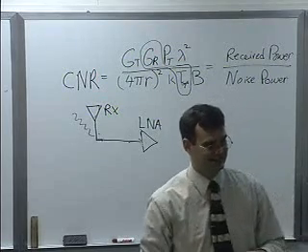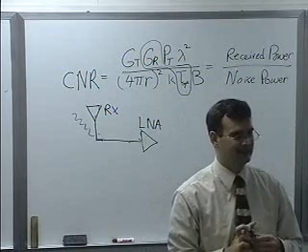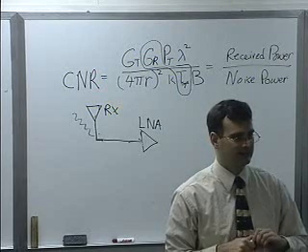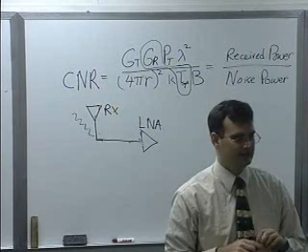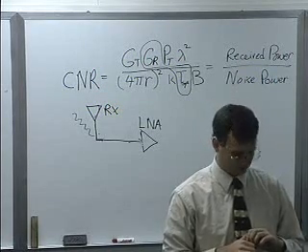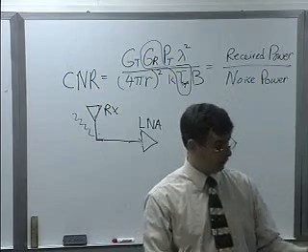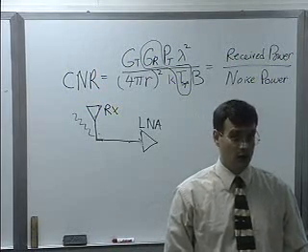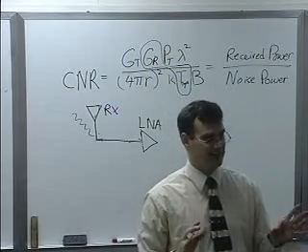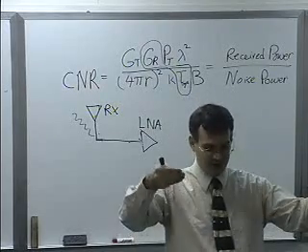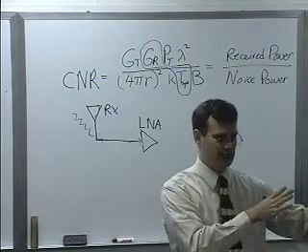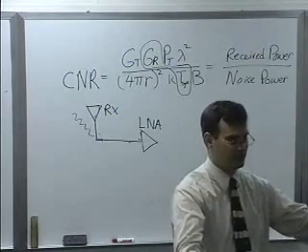Yeah, Grant? Licensed 10 gigahertz area or the ham area, and so you might not always have active transmitters there, but won't you always have people who have harmonics of whatever system they're using? There is the potential for harmonics, although hopefully, if they're not violating any FCC regulations, the harmonics themselves will be pretty low compared to the actual transmit power that, say, the 10 gig transmitter is transmitting.